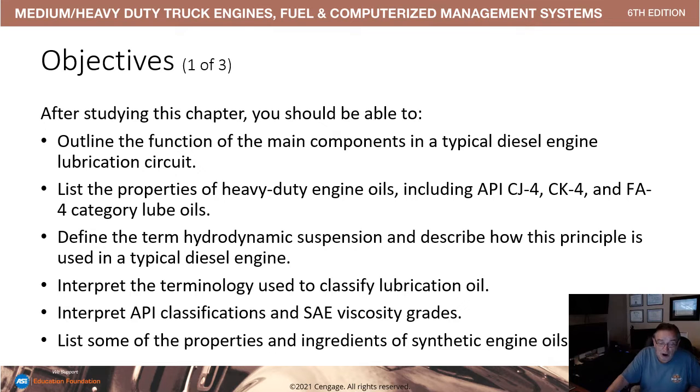Define the term hydrodynamic suspension and describe how this principle is used in typical diesel engines. Interpret terminology used to classify lubrication oil. Interpret API, American Petroleum Institute, classifications, and SAE, Society of Automotive Engineers, viscosity grades. List some of the properties and ingredients of synthetic engine oils.